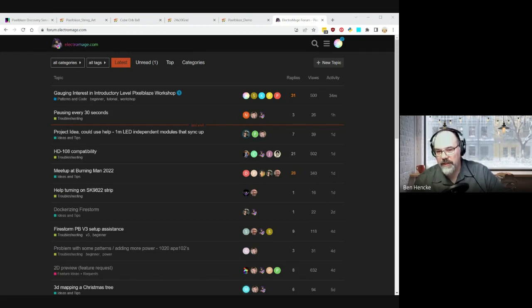You could use either. The APA102s are usually a little bit more expensive, and there are fewer form factors available for them. But if you have something like a panel or an LED strip, or like the Lux Lavalier, which uses those kinds of LEDs, it's really great for anything that is wearable, where you're dialing down the brightness. You're not trying to blind people, but still want to be able to get color depth. So I'll turn it back to you now.